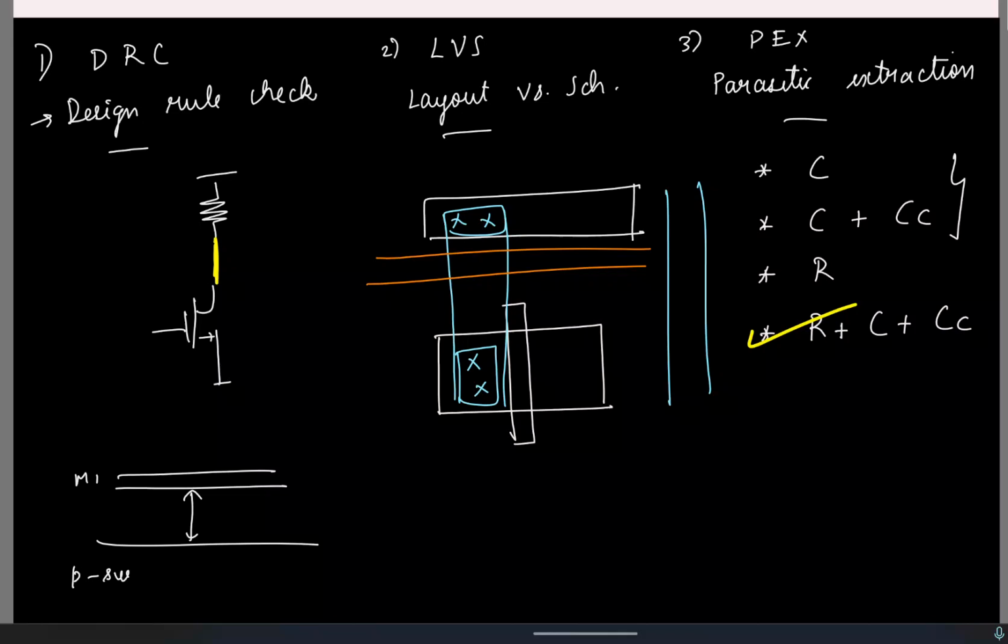So what I will be doing is, from each net, I might have some parasitic capacitance to ground, some coupling capacitance to this node and so on, right? And basically I'm not changing the number of nodes, the number of nodes is still the same. From that node I'm just estimating the capacitances to all the other nodes.